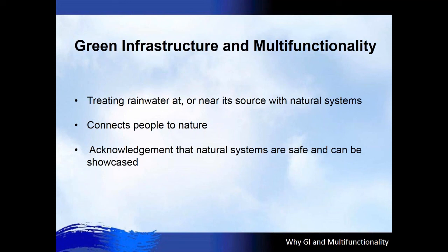And when you start looking at how much land it takes to do green infrastructure, or where green infrastructure can be folded into other land uses, it really makes sense to look at a multifunctional solution versus just here's the detention pond over there and then the park is on the other side of the site. Instead, why not make that into a single multifunctional facility? Yeah, we'll see how well I can keep up the stormwater versus rainwater terminology.